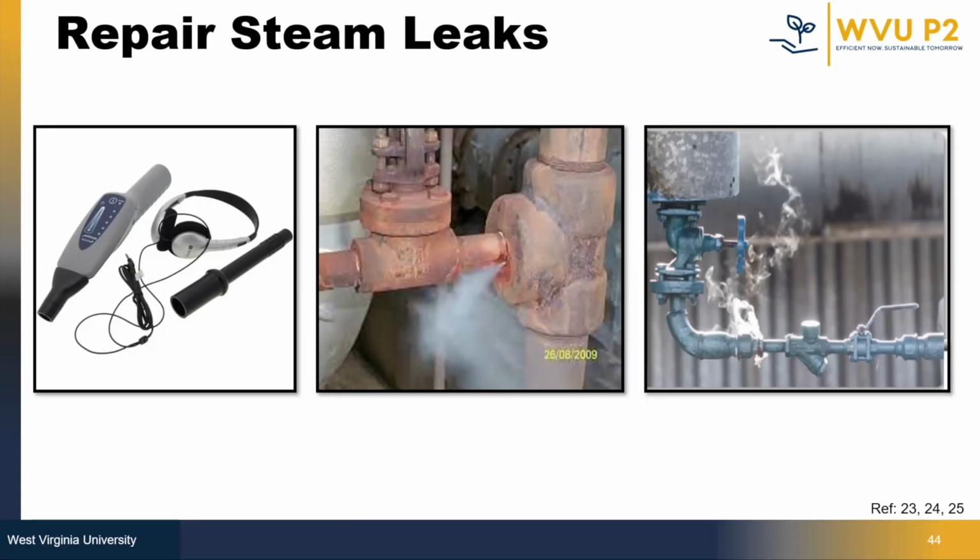While steam leaks are often visible and audible, some may not be immediately apparent. The pipes may be close to the ceiling or otherwise not easily visible, and a noisy environment may mask the sound. So, an ultrasonic leak detector can be used to help locate these leaks by detecting ultrasonic noise associated with the pressurized leak. They are very simple to use and really affordable.